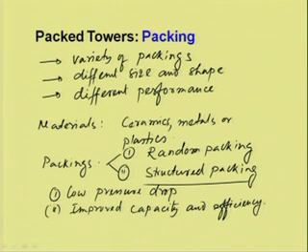The disadvantage of structured packing is that the cost is relatively higher compared to random packing, and generally this packing is preferred where we need a specific arrangement in the packed towers.